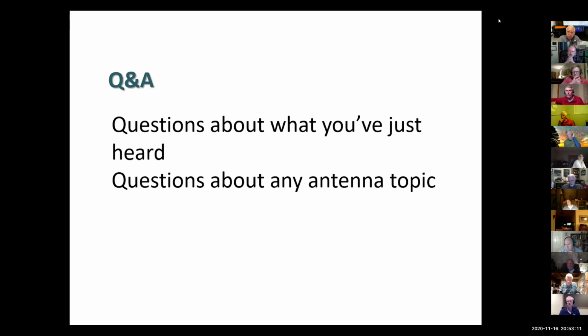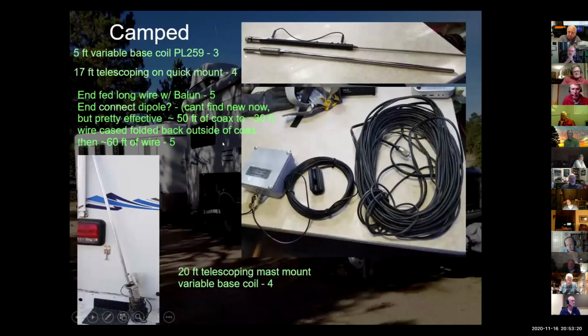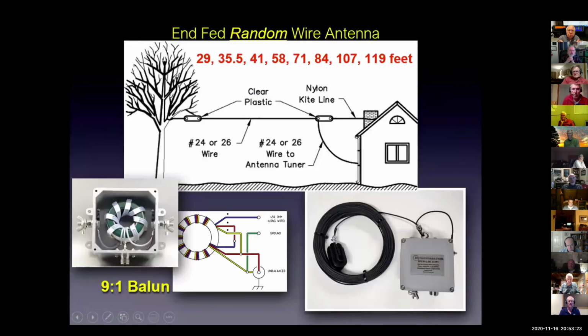I've got a question. Steve showed those links that were non-resonant, and I think it's kind of counterintuitive, because we hear that we want an antenna that's resonant on the frequency we use. It also relates to something I've been looking into putting up, because if I'm going to string some wire, I want something multi-band. I've been looking at the off-center fed dipole, and I think the same principles apply to that type of antenna, where you choose a length that is not resonant.